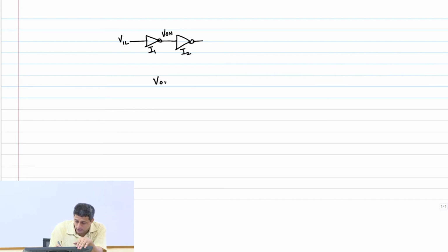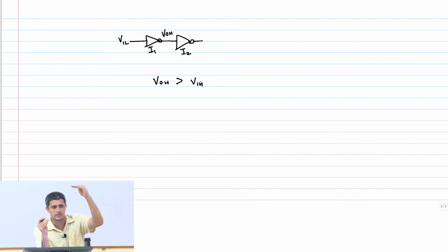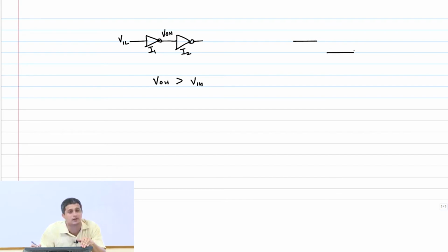Correct. VOH should be greater than VIH, which means that if there is a noise pulse up to this magnitude, the difference of VOH and VIH, it should be fine. My VOH is somewhere here. My VIH is somewhere here. This is VOH, this is VIH. VOH is above VIH. As long as that's taken care of, it's a logic high, no problem.